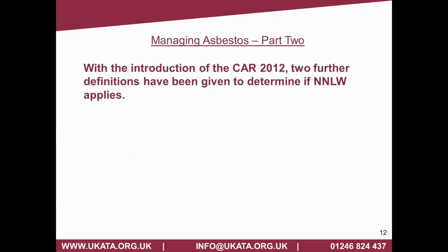With the introduction of CAR 2012, two further definitions have been given to determine if the works is notifiable non-licensed works. These are defined as: is it classed as maintenance works or is it classed as removal? Now, if it's removal and the material is being removed where the matrix is held in place whole, then that would be classed as non-licensed works. But if the removal is going to degrade the product, then it would be classed as notifiable non-licensed works. But the maintenance one is the key one.